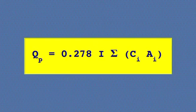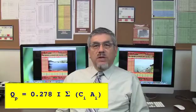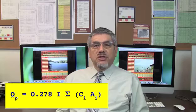When a clear pattern of variation is apparent, a weighted value is applicable. Individual sub-areas are delineated and their respective runoff coefficients identified. Areal weighing leads to an expression in which rainfall intensity is in millimeters per hour, area in square kilometers, and peak discharge in cubic meters per second.